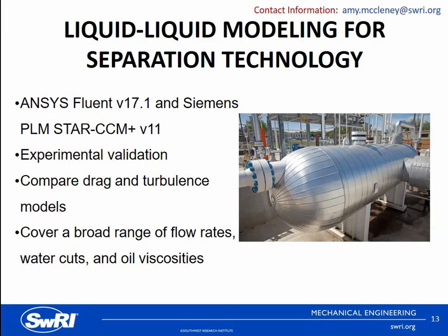So I'm about to go into some of the CFD work that we accomplished here at SWRI looking at liquid-liquid separation for horizontal gravity separators. This was conducted in both ANSYS Fluent and Siemens Star-CCM+. This was mainly a parametric study to determine the best modeling approach in each software package, not necessarily which software performed better than the other.